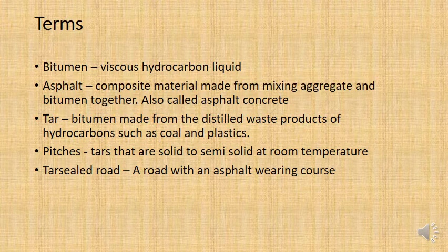But this is where it gets a little bit confusing. What's a tar-sealed road? Well, it's basically a road that has an asphalt wearing course. Many years back in the 1910s, 1920s, that asphalt would have been aggregate mixed with tar. And so that's why we call the road a tar-sealed road. These days, we never use tar for roads anymore.